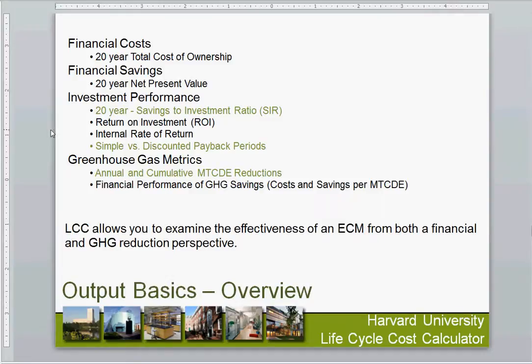Every once in a while, not very often, it makes sense to pursue something that has a great reduction in emissions, even if it doesn't have the best financial payback. An example would be a major overhaul of a building that might be uninsulated. Retrofitting anything is very expensive. If we were just building a new building, the cost of insulation is relatively cheap, but to pull away interior finishes back to the studs or the wall, insulate, and then completely recreate that wall is a very expensive endeavor.